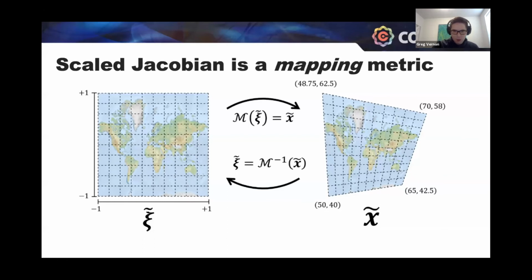If I look at the map on the right, if you were to give someone this map and say, here's Paris, and you didn't show these little iso curves that show you which direction's north and which ones are east or west, and now you asked them to tell you which direction was north and south and east and west, that would be harder for someone to pick out. And so in the same way, the larger the deformations of our elements are, the more the computer has to think about the solution, and the more the solution can potentially degrade. So that's a good mental model for what scaled Jacobian is and why it matters, and why it's a good general purpose metric. Hopefully that's helpful.